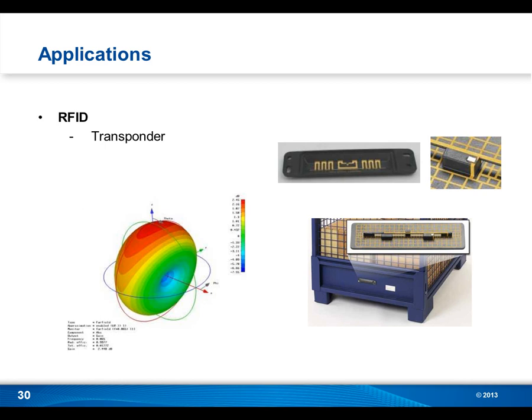So using the entire three-dimensional surface of your package to create these long, thin conductive lines fits well with LDS. The other side of this is that it can be used in a fairly harsh environment, either a manufacturing environment or harsh operating environments. And encasing it in a plastic and having it all part of a plastic case is advantageous in that situation.